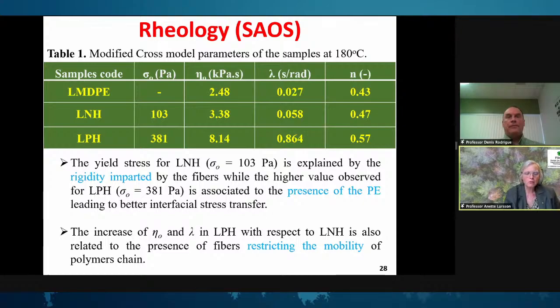Was that valid for all different thermal processing techniques? Or could it have been compression molding? Should that have worked? Yes, it was actually borderline a little bit. We were able to produce some parts, but it was not very good actually. So again, it depends on the application that you're looking for. So do you think the 80% of bio-based materials is the upper limit? We did a little bit more, I would say up to 85, 90. It depends on the surface treatment and the type of matrix also.